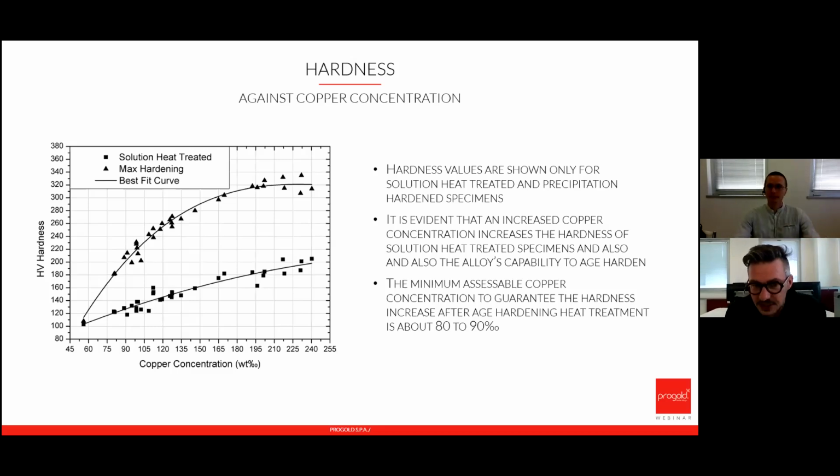It is not easy. It's quite impossible. This is a natural defect because, as you know, to get the right temperature for the soldering phase, you need to drop the melting point. To get red gold or pink gold, we need to put in a lot of copper, and to reduce the melting point, we necessarily need to add other materials which change the color of the red gold. The lower you want the melting point to be able to make soldering, the higher will be the loss in terms of color. So it's not a point that we don't have, it's a kind of natural limit.